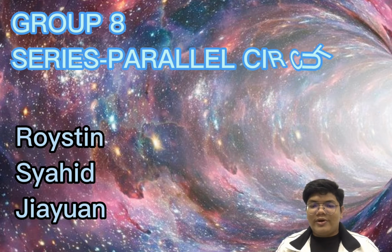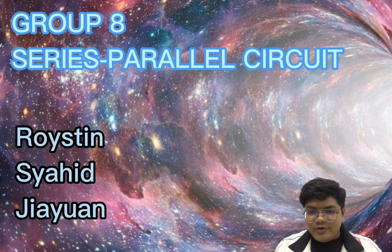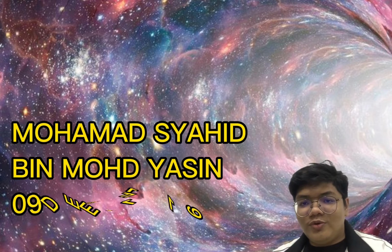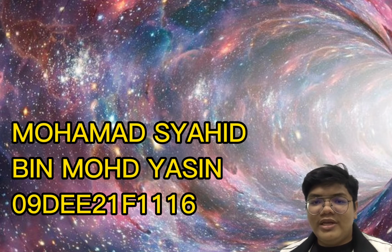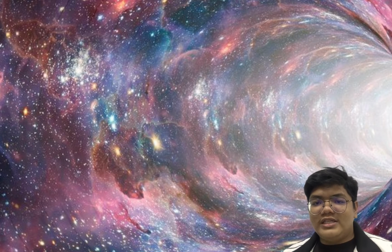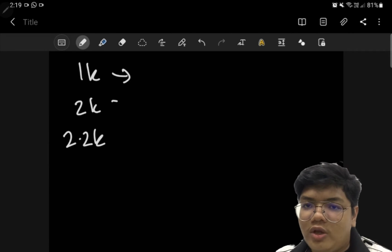Assalamualaikum warahmatullahi wabarakatuh. Sorry for the interruption. Today, I, representative of Group E, Muhammad Syahid Muhammad Yassin from the AA1C, will introduce you to the presentation of series and parallel circuit. Firstly, we need to determine the color code of the resistors that we need to use. My group have decided that we will use 1 kilo ohm, 2 kilo ohm and 2.2 kilo ohm.